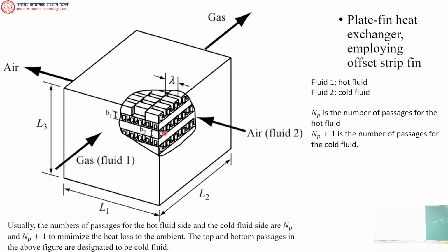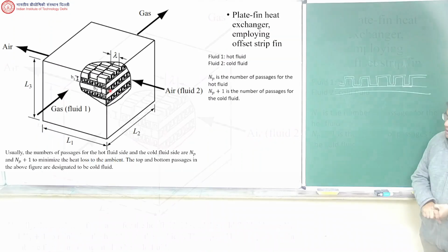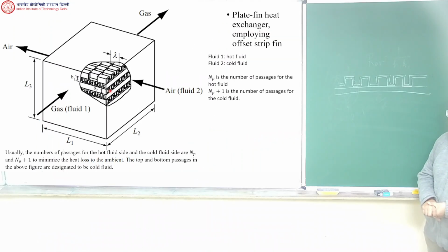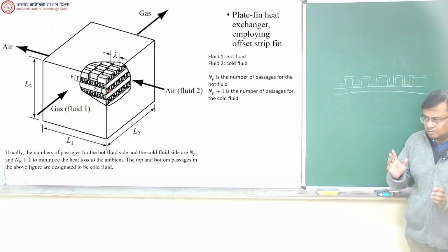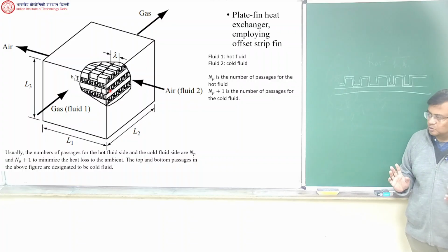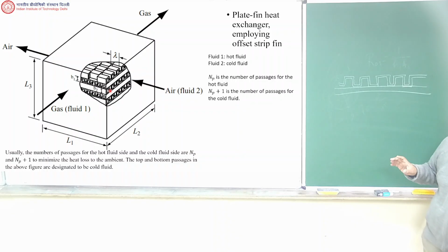And gases give you low heat transfer coefficient. We had a discussion on that quite some time back. So they need fins. And since both are gases, both require fins in the surface. Right? So that's one thing. It makes the geometry more complicated. So we will need to have a careful look at this geometry to be able to define both the areas. We need an area A1, we need an area A2. Ultimately, it will still come to that UA calculation. Right?